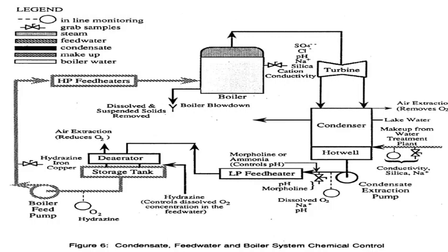The final stage of dissolved oxygen removal is by the injection of hydrazine actually, and that is done between the deaerator and the deaerator storage tank. So to chemically control the dissolved oxygen.